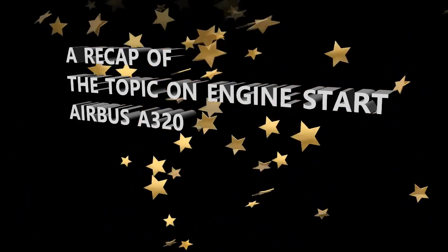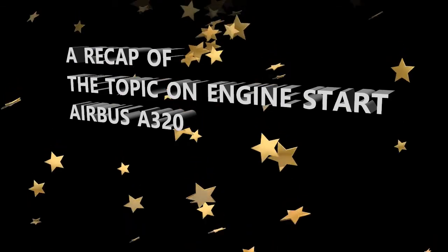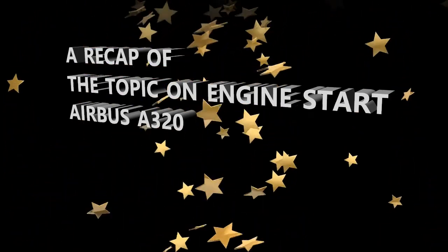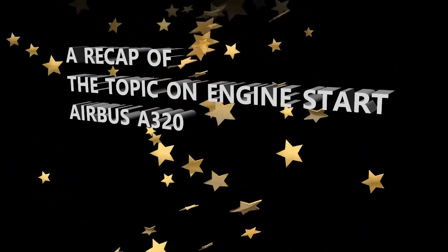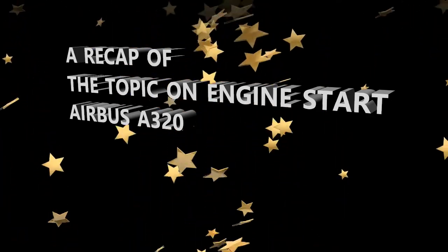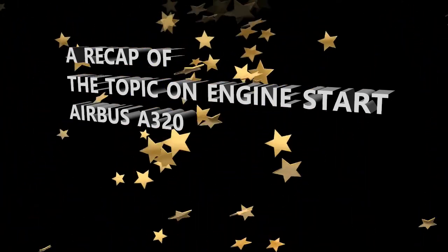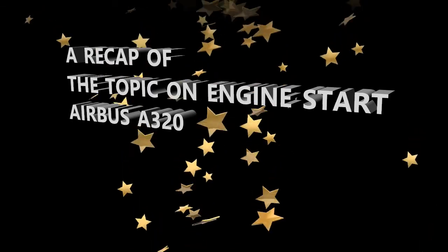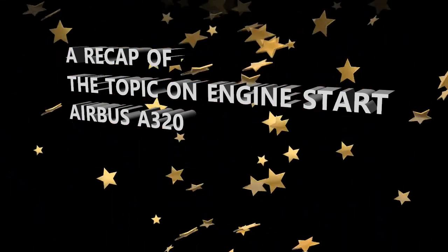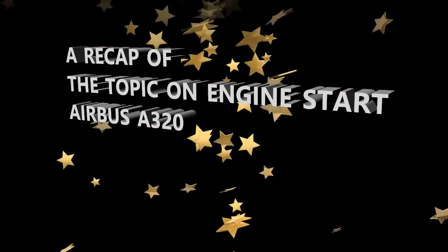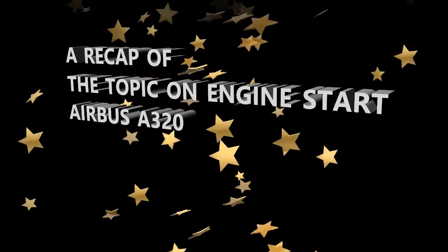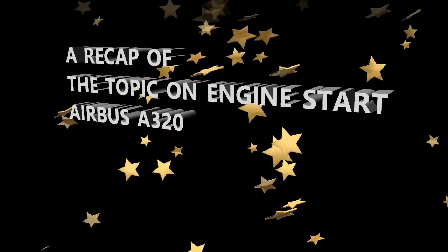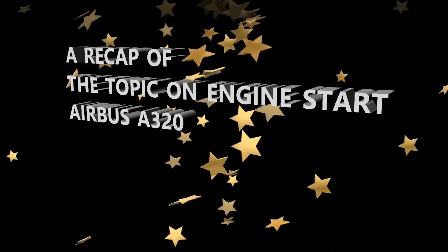You can have the EGT, engine exhaust temperature, that's too high, so you have an exceedance there. Another fault could be that the starter time is exceeded, going past how much it should take to actually start. So that's a fault right there. So we covered some of those.